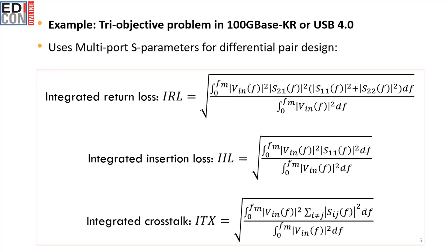Here, the input pulse could also be band limited. It could be 0 outside of some band, and that could certainly band limit the channel. The point here is that in these integrated signal integrity metrics, you're considering what happens over a very broad bandwidth. This is actually the approach that I take in what I'll show here for transmission line design: you want to be able to consider the very broad bandwidth, not just one frequency. It's kind of unfortunate because most solvers will only consider what happens at one frequency and leave you to figure out the rest.